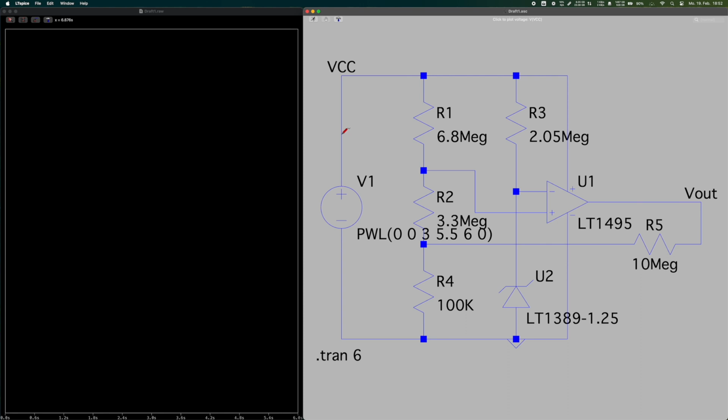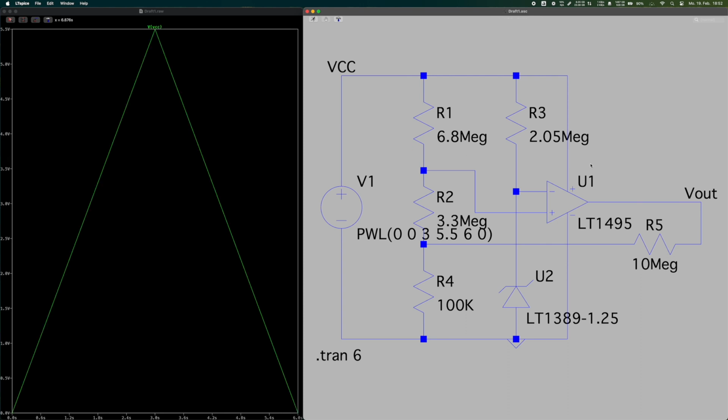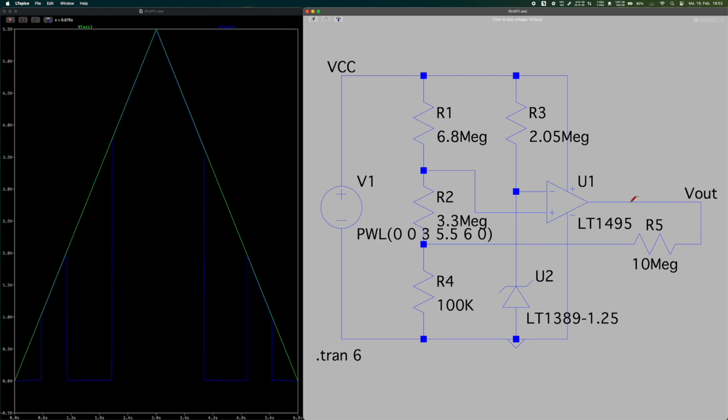This time I decided to simulate the circuit using LTspice before making a PCB. This proved to be the right decision because, as it turned out, the circuit would not behave correctly for voltages between 1 and 2 volts and actually enabled the output when it was not supposed to.